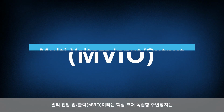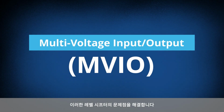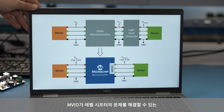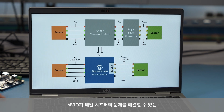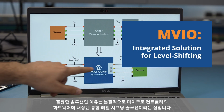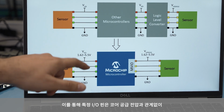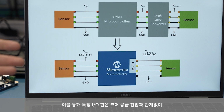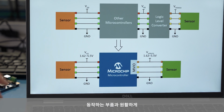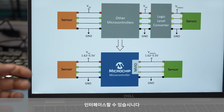We have a core-independent peripheral called multi-voltage input-output, or MVIO, that addresses the challenges that discrete level shifters have. Here, let me show you. What makes MVIO a great solution to the challenges posed by discrete level shifters is that it is essentially an integrated level shifting solution built directly into the microcontroller's hardware. This allows specific I/O pins to seamlessly interface with components operating at different voltage levels independent of the core supply voltage, whether it's higher or lower, across a wide range of voltages, all without requiring any external components.